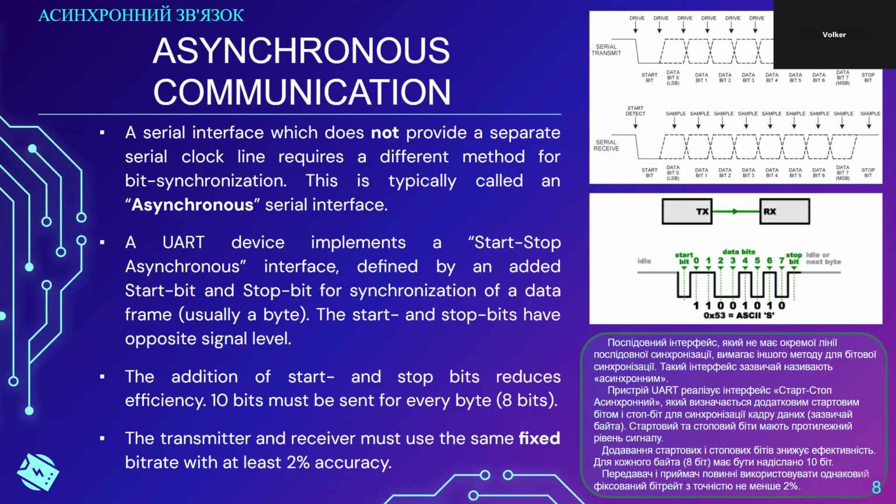If people have worked with older microcontrollers, for example, the 8051 series, which I believe is still fairly popular in Europe and also in Eastern European countries, sometimes you will see a strange crystal frequency, 11.0592 megahertz.